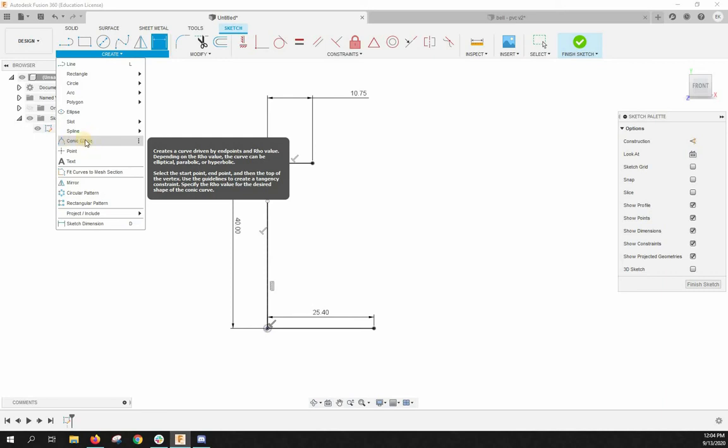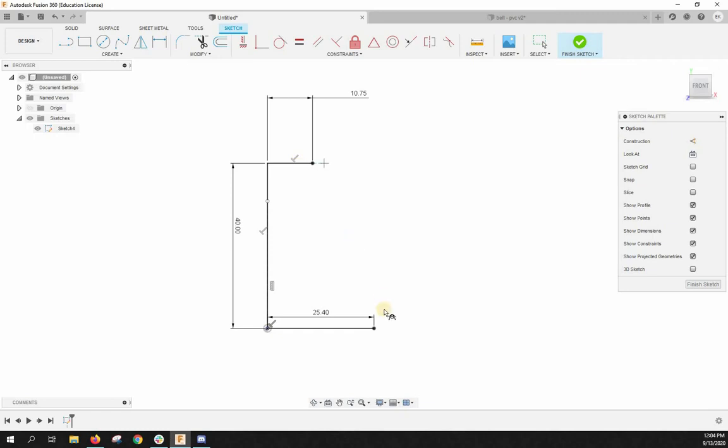So we're going to click that. You can click these in either order, but I'm going to click this point, click this point, and then drag this anywhere. I'm just going to do it so it doesn't have any auto snaps. Click that, and you're going to see this pop up here for the rho. I want the rho to be 0.5, type 0.5, and hit enter. And so there's my rho value.